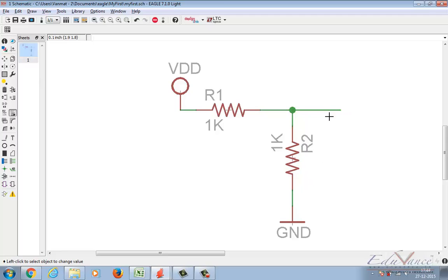What if I want to name a wire? How do I? You see this tool out here right next to your junction tool. It's called the label tool. This helps you to name wires and not components. You realize the significance of this tool when you are making bigger complex schematics. But let's just see how you can use it.